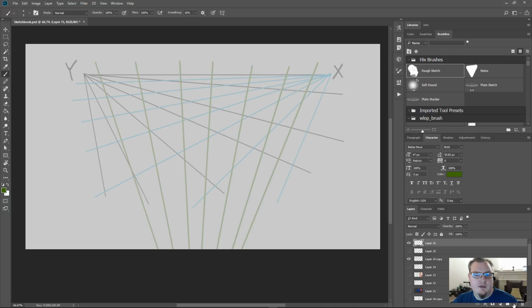And then up here, let's draw here. So what we would do in this case is we would pick a corner for a building. Let's say it's right about here. Let's say we want the other side of the building to go out to there. It's the same rules as the 2-point perspective, and the only thing that changes is when you get to the verticals. So now what we want to do is follow the guidelines back to the vanishing point that's off the page now.